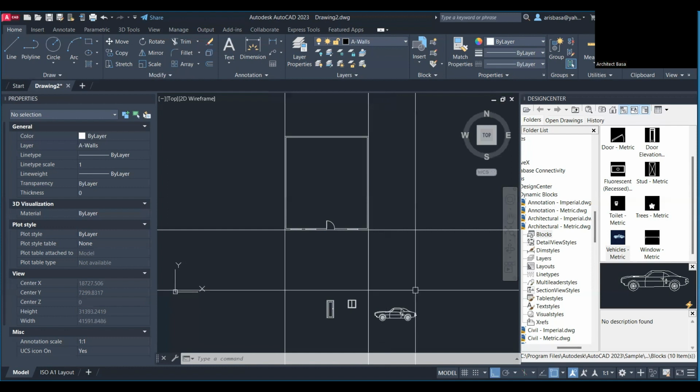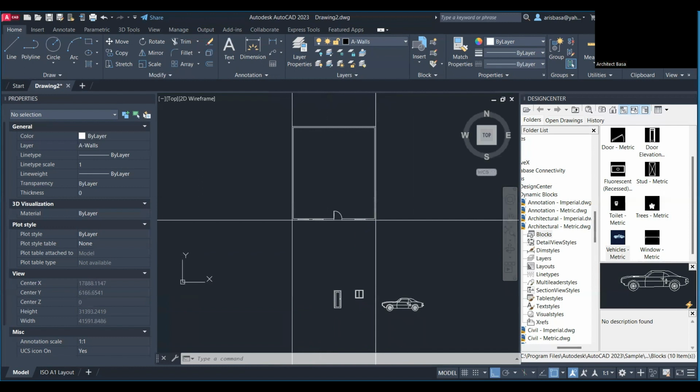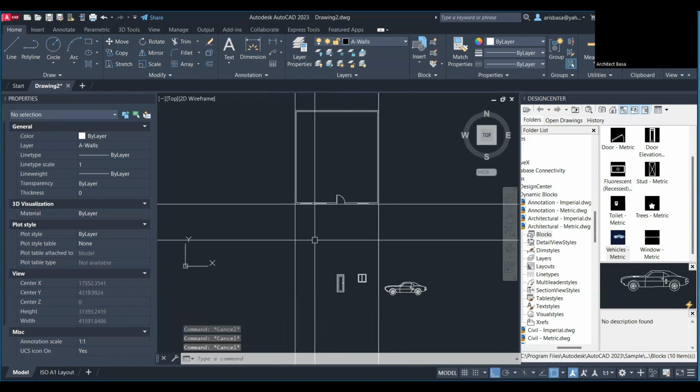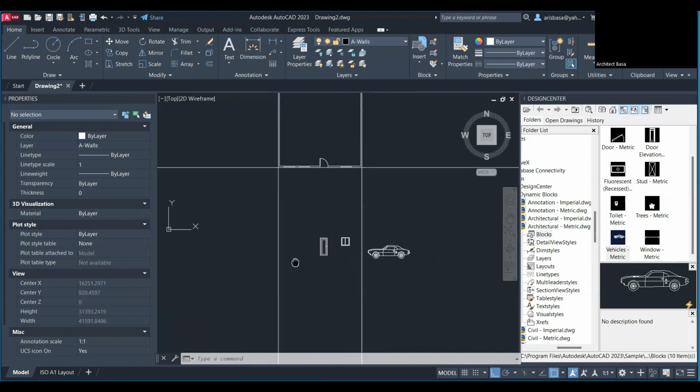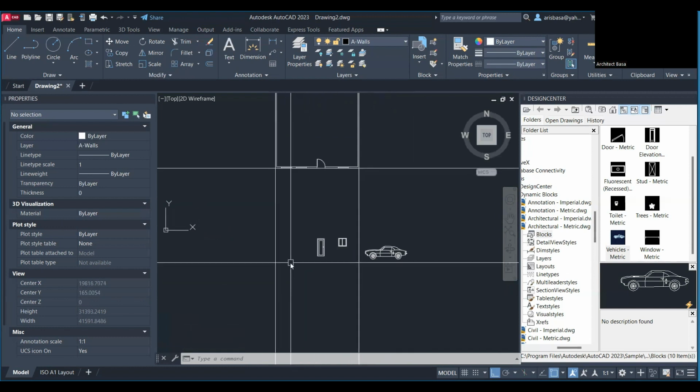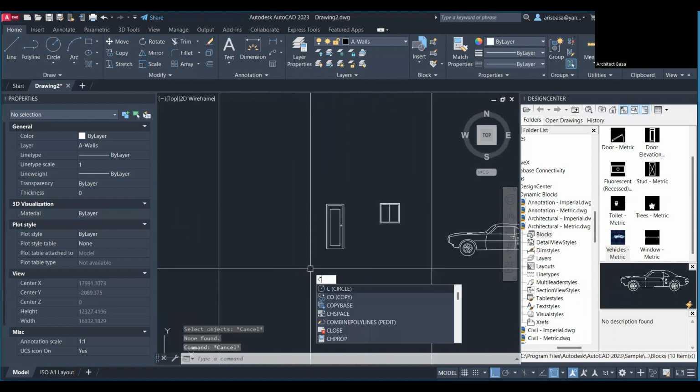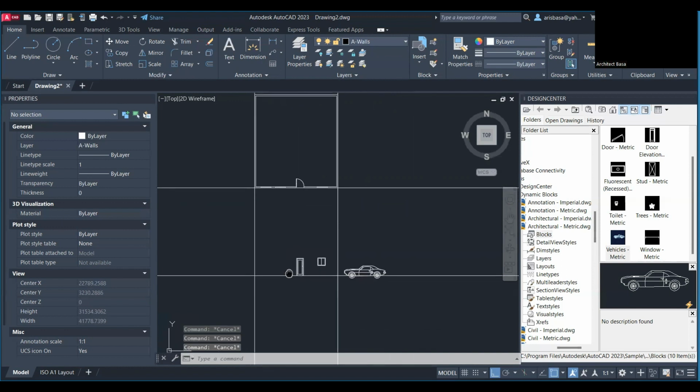Okay. So let's go back. So you now have the reference line for your wall. Okay. And usually you need to have a reference height for your building, a horizontal reference line. So we'll do again another X line, and click it here by the door. Okay. And just click it that way. Okay. That will be the bottom of your line.